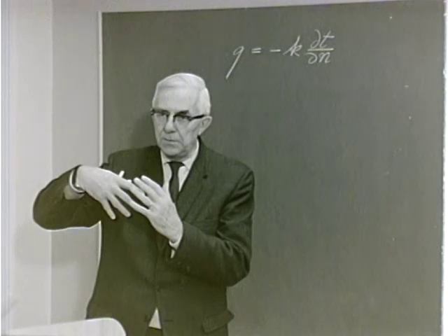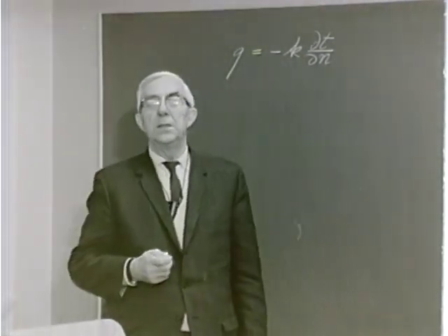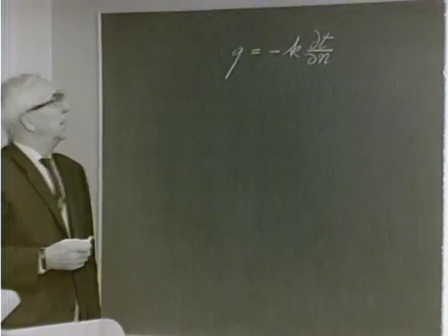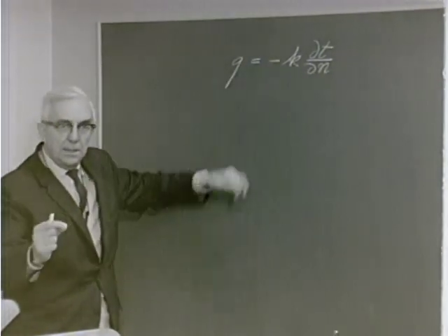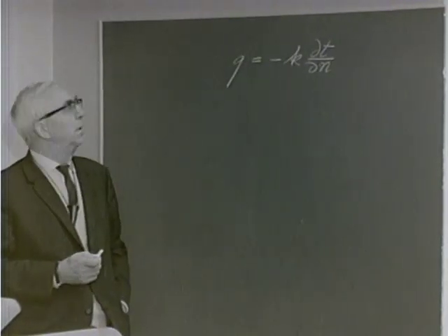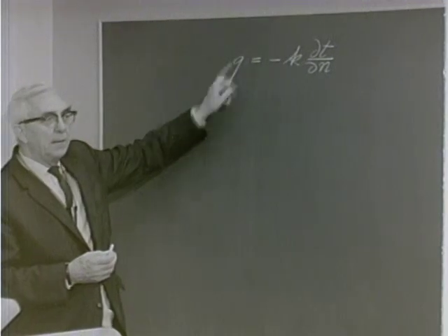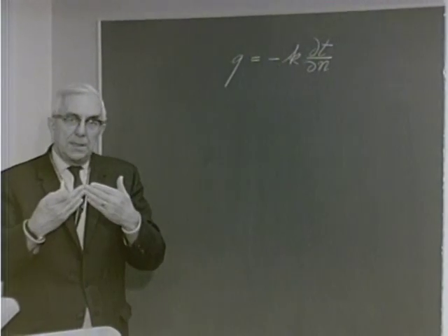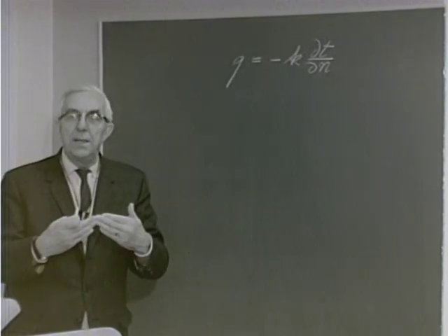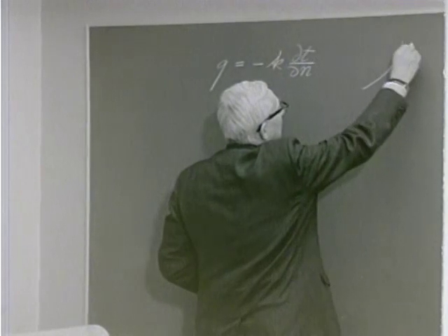If the situation is unsteady, these surfaces will move through the solid material. To calculate the heat flux per unit time and per unit area at a certain instant and at an arbitrary location in the solid body, we think of the temperature field frozen at this moment.